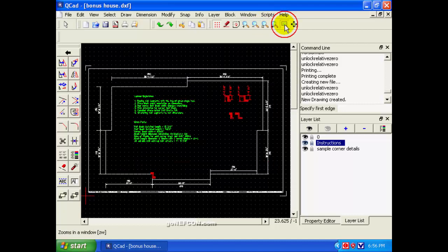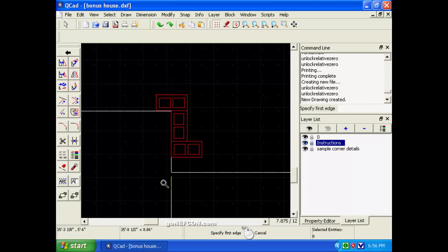Many people mistakenly feel that, well, if it's a 2-block outcrop, then it must be 2 blocks wide, but that's just not the case. Here's our 2 blocks, and you notice that the wall turns here, goes down here, and goes there. This is 2 block lengths right here, 4 half blocks. So that's just not true, because the wall doesn't include this half block here. So the wall is really a block and a half. The offset's a block and a half.